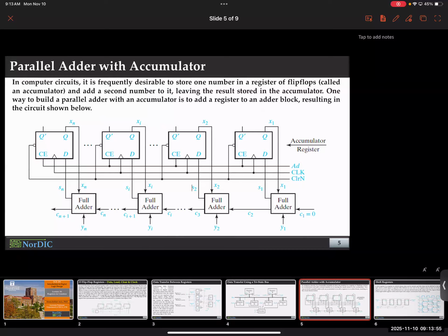I don't know if you realize this is the first slide that brought together combinational logic and sequential logic in a real system. But when we went over the adder lecture, we only looked at adders. We didn't even consider the need to store an intermediate result. And for this slide, we noticed that you could always save the sum from every stage and add it back during the next cycle. So there is a concept of previous cycle, next cycle, which was not there in combinational logic because combinational logic doesn't have any history. Okay, that's how combinational logic and sequential logic work together.